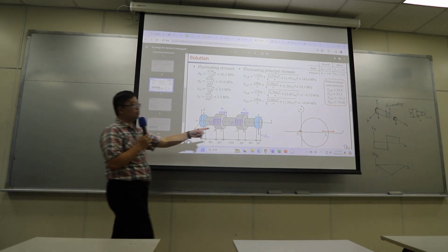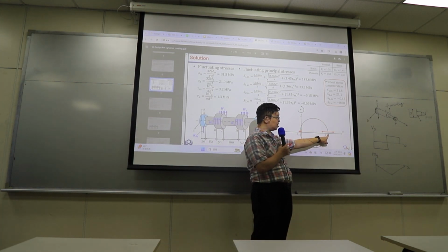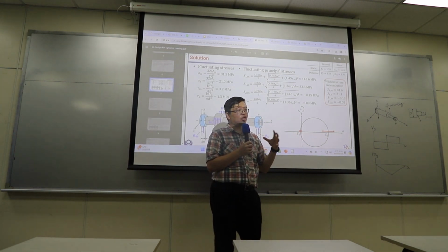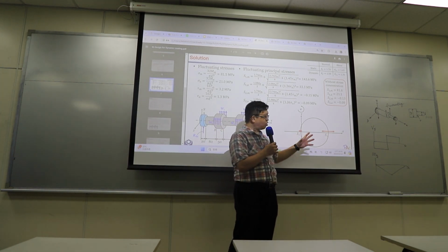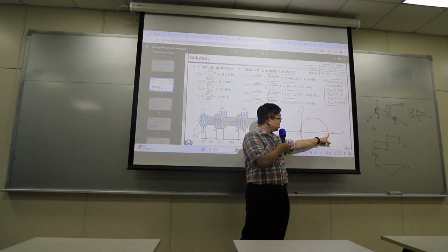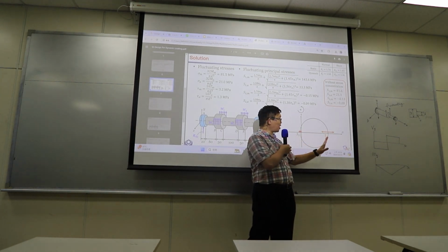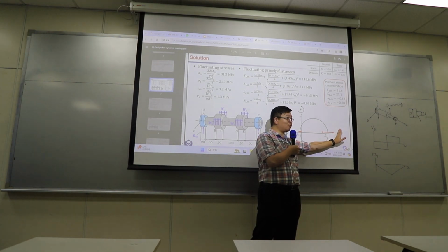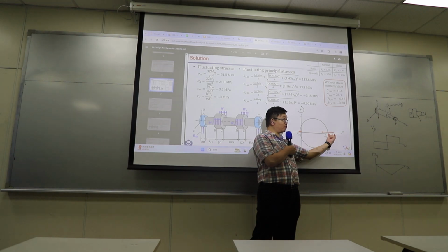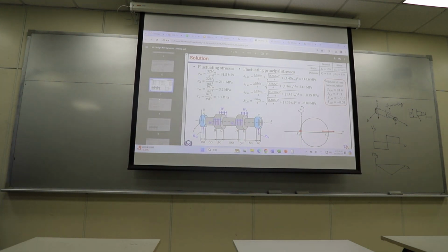Mohr's circle, because for von Mises stress, you need Mohr's circle to find out what the principal stresses are. And because the stress changes with time, Mohr's circle changes with time. So the first principal stress changes with time. Sometimes it's low, sometimes it's large. So figure out what's the mean value. Figure out what's the amplitude. Use it for von Mises stress.